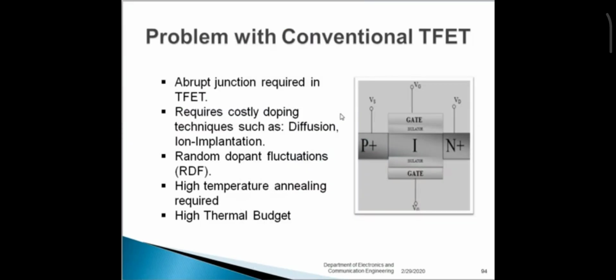Last one, there are some problems in the conventional TFET. First, the major problem is that an abrupt junction is required in a TFET. Second, it requires costly doping techniques such as diffusion and ion implantation.